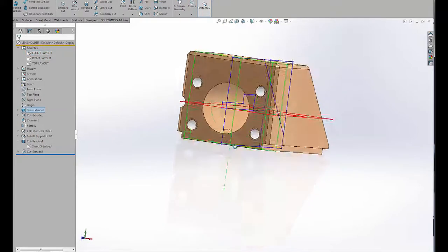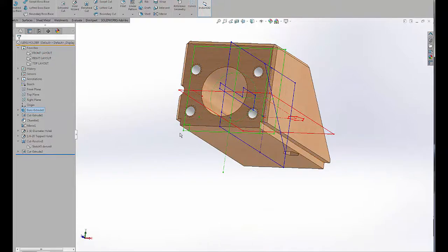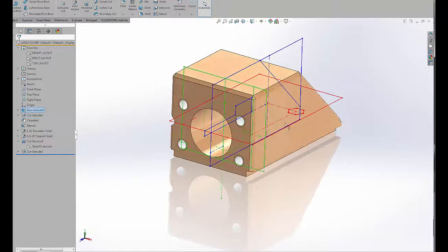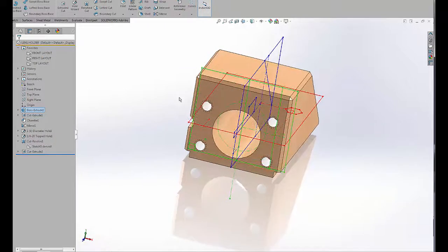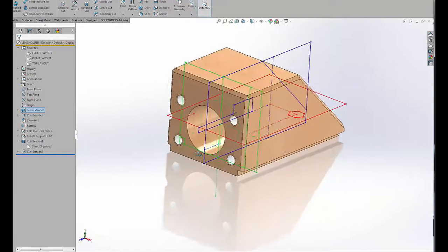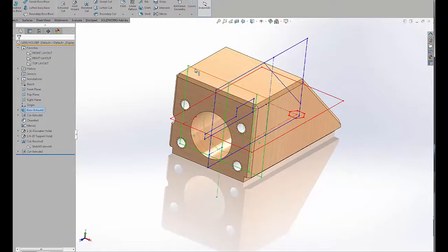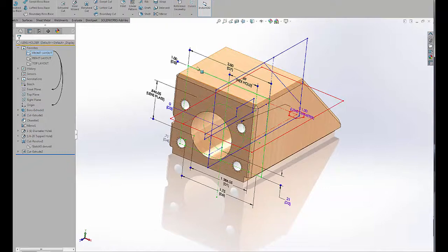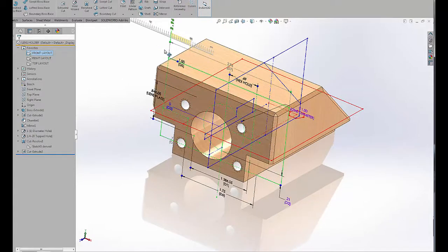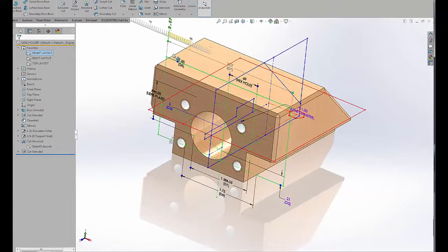And how about down here? This width. Does this shoulder ride in something else? What happens when I change the width of this whole part? Does this shoulder move wider with it, or does it stay? So let's just see what happens. If I change the width, okay, so I see that the shoulder stays the same, but also that it gets higher by the same amount. So now I know the design intent for this part.